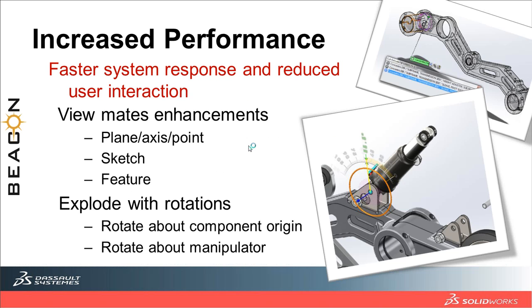One more modification has been the addition of the rotation in terms of exploding. What I mean to say is, let's say, for example, you are creating an exploded view. So initially, till now, what we used to do was we used to get a triad, and by the triad you used to get a linear translation. But now in 2014 onwards, along with the translation, I can rotate those particular components as well. And this will save me a lot of time in case I need to make a video of, let's say, how a particular assembly is being assembled or disassembled. We'll have a look at this.